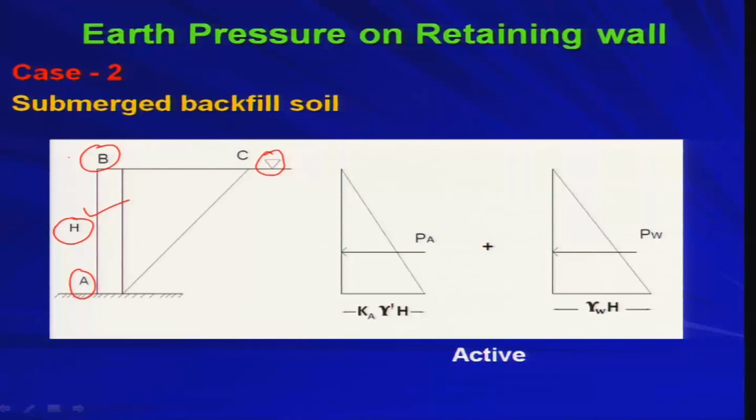When you consider the soil, you get the active thrust or passive thrust depending on the situation, but in case of water it gives you the hydrostatic pressure, simple. There is no active or passive in case of water pressure. It gives you all round hydrostatic pressure. In case of the active state, we can still consider that. So, your sigma v is